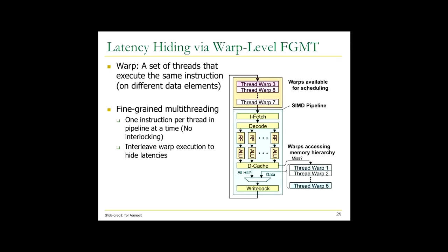Remember, a long time ago, I showed you the heterogeneous element processor. It had these queues. There was a fetch queue, with threads waiting in it. Now we have these threads, but threads are grouped into warps. If a thread gets a cache miss, for example, and needs to wait for memory for 1,000 cycles, you take out that warp and move it into this waiting queue.